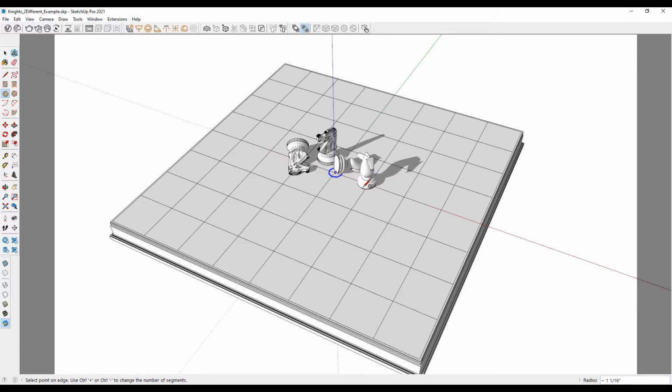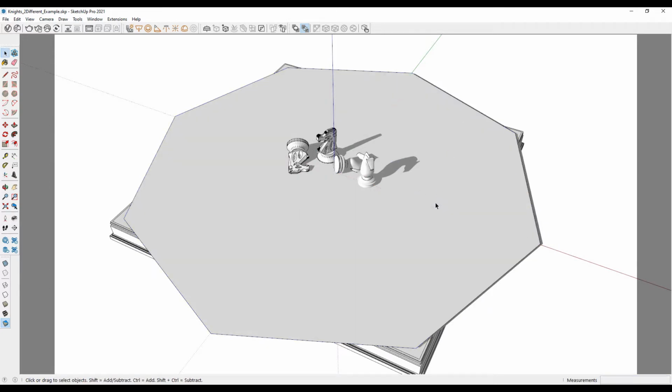So now I'm going to click and drag, and notice I'm dragging along the red axis here. I can also drag it on the green axis. I just recommend that you always do that, so in the future when you need to edit anything about the circle or the multifaceted object, it's easier for you to do so, right? So for the sake of this example, I'm just going to pull it all the way up to this end here, and I have that plane that's drawn in.